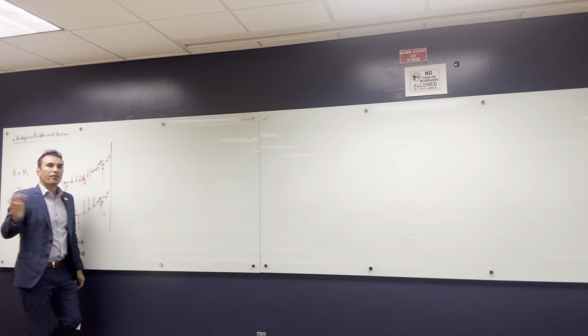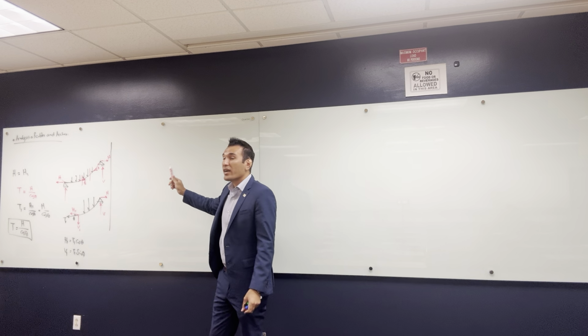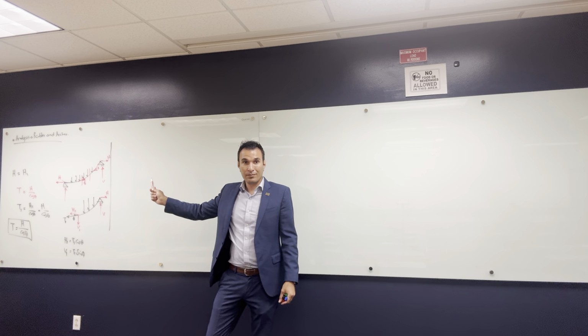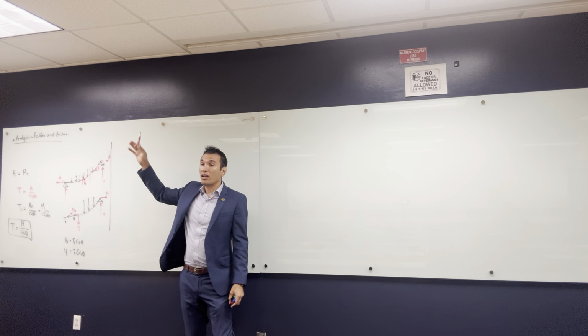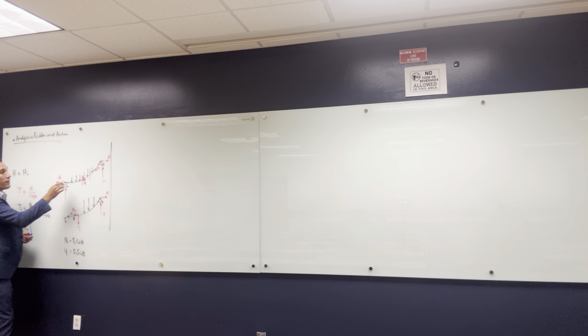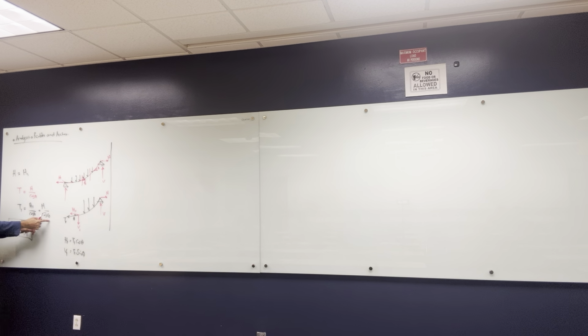All right, then we started talking about where I can find the maximum tension. Do you guys remember? The maximum tension is at the maximum theta. If theta becomes 90 degrees, cosine theta is going to be equal to 0, and this value is going to be infinity. The tension is going to be infinity. So that's the maximum. And what is the lowest? When theta is equal to 0, like here, cosine 0 is equal to 1, so the tension is going to be equal to the horizontal force.